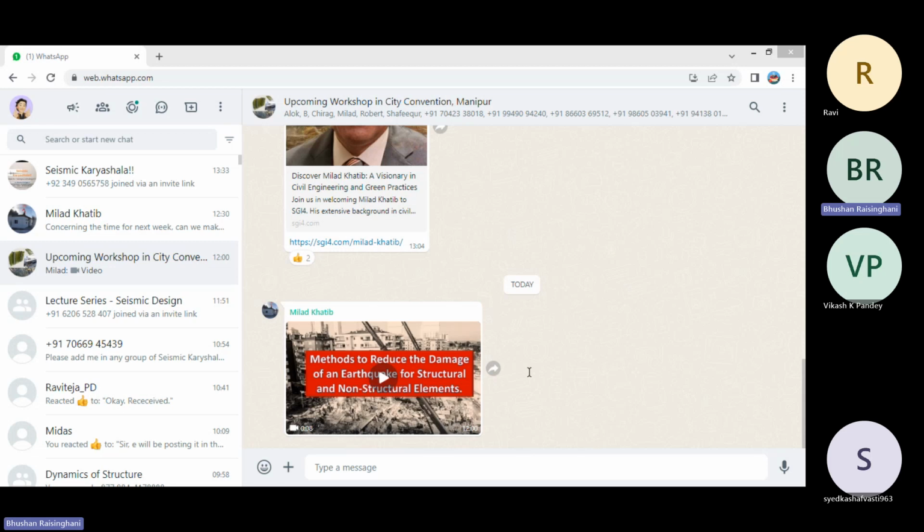And if the full wall is acting as a ductile wall with special confining reinforcement, then it has to follow the regulation as per section 8 of this code. So that was related to boundary elements. Where a boundary element is not required, that means the full wall is ductile detailed as per section 8, which will complicate your concreting.